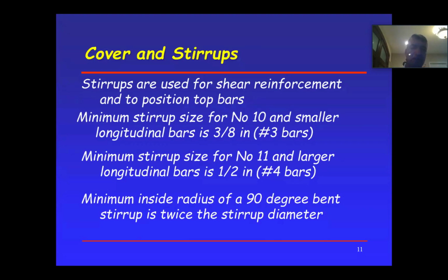Okay, cover and stirrups. See that? If you notice, we are defining some terms before we start designing the beams. This is what we need when we start designing. So what is cover? Remember, the cover is how we're going to cover the rebars. And remember, in beams, I told you that distance is 2.5 to 3 inches from center line to the bottom of the beam. You will see in the slabs it is much less than that, like 1.75. But we'll see those. So that's what the cover is.